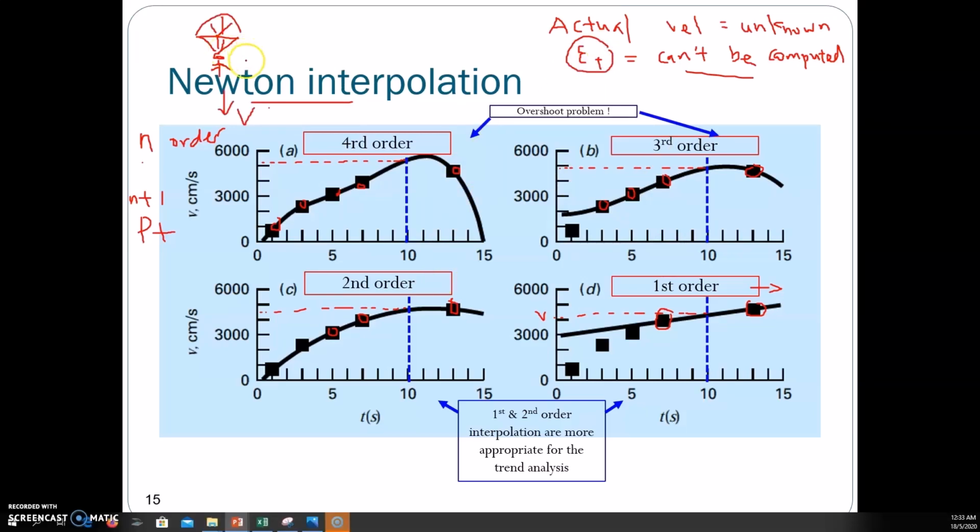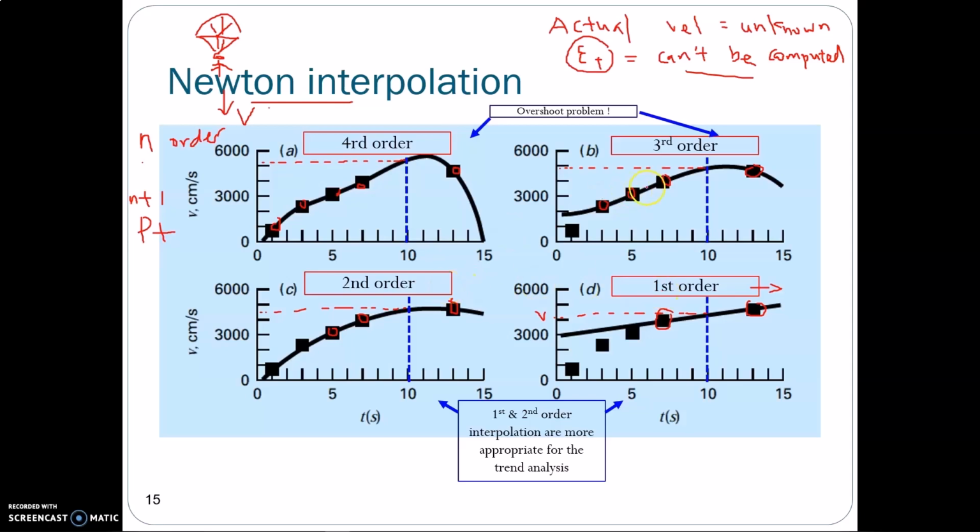In this case, we need to take the physical consideration of the falling parachute case to evaluate the appropriateness of this result. From Newton's law, mg minus the drag force is equal to ma, and a is equal to the first derivative of velocity. When the mg is larger than the drag force, in this case, the mass will experience the change in terms of velocity, and the velocity will increase over the time. So this is the transient process where the velocity is changing.